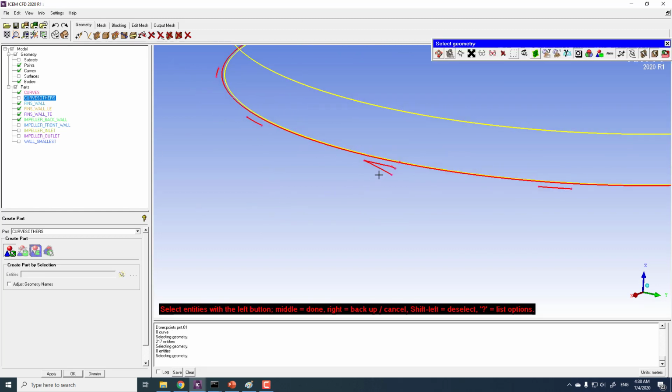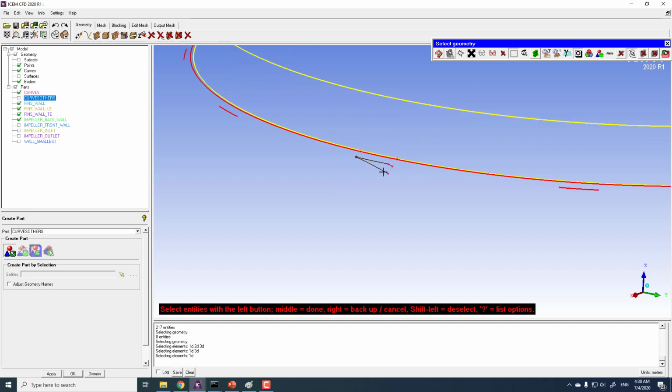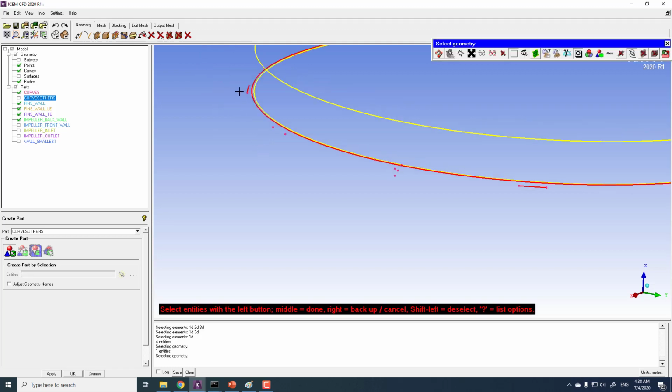and then I would try to put these parts also, which are here. But this time what I'm doing is that I should be unchecking the option for the points and surfaces and also bodies, and uncheck this option as well, and now I can use this whole box, and still not be able to select these curves from here. So I can select these curves which are smaller here, and this internal curve as well.